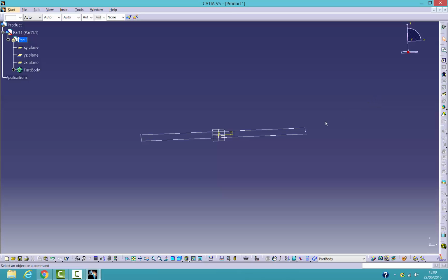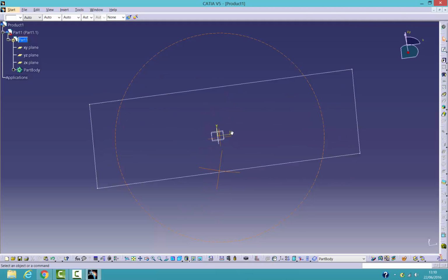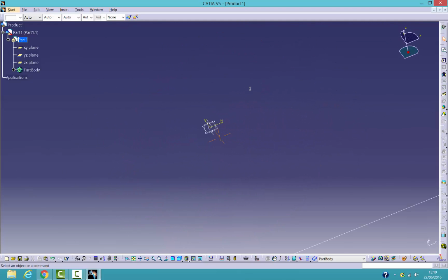After this we've got the middle mouse button held down with the right mouse button held down. Then you release the right mouse button whilst holding down the middle button still, and you'll get a zoom function. Now this can be combined with clicking on the right mouse button and holding that down. You see what I mean? You can now have a look around, zoom in on parts, and it's really useful to get used to this. It can make creating parts a whole lot easier, instead of going into zoom mode.